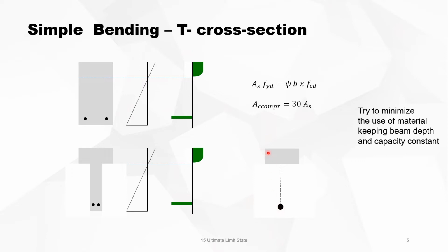Of course, you can go one step further and then you only have a compression zone and a tension zone, but they have to work together. So that's why there's a dotted line. But these kinds of structures do exist, where this is steel, or a rod, just a tension rod, and these are spacers, and this is a compression zone. So this type of beam has been used in the past. But the T-section is in fact nothing more, nothing less than an optimization of a rectangular section.